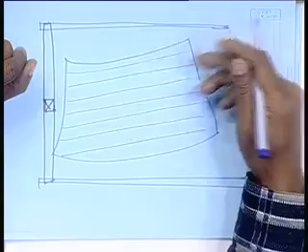If it has to be straightened, then it is a little difficult, you probably have to turn the plate. But if it is underbent, further bending is to be given, so a new set of heating lines is to be generated. So based on that comparison, a new set of heating lines, if required, will be generated, you apply that heating again, and eventually you get the bent shape. That is how it is done.